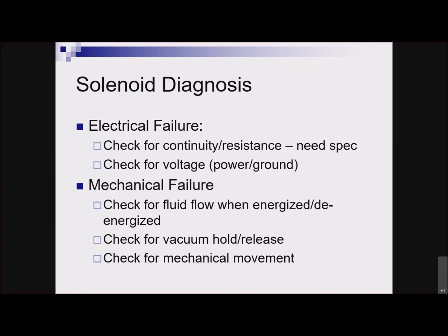If it's a fuel injector, it's a little more difficult because those are typically inside the intake manifold, inside the fuel rail. If you remove it from the car and try to test it on the bench, then you don't have any fuel pressure attached to it. So we can do things like injector flow testing. I think you probably did that in fuel and emissions, where you check the vehicle's fuel pressure and then you energize an injector and see if the fuel pressure in the rail drops. It should. If the injector is open, letting fuel out of the rail, the pressure should drop. If it doesn't, then the injector's not flowing.